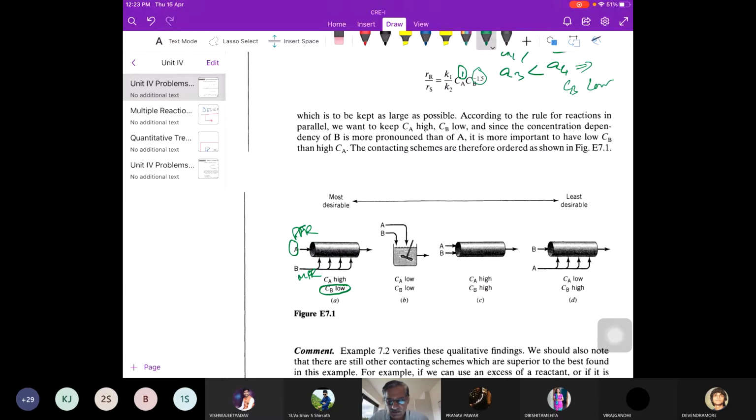यस सर. What is yield? टोटल रिएक्ट हुआ उसमें डिजायर्ड के लिए कितना रिएक्ट हुआ. Exactly. So if my conversion is 90% and my yield is only 50%, it's a waste of my raw material. But if my conversion is 70% and my yield is 90%, I'll be happy with that. और बहुत सारे रिएक्शन में ऐसा होता है कि conversion is hardly 10, 20, 30%, but yield is high. Because you can recycle the unreacted reactants, but जो product आएगा, जो बन जाएगा undesired, उसको waste जाता है, उसका कोई use नहीं होता है.